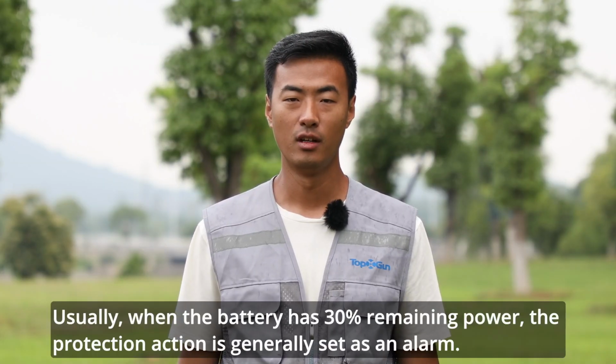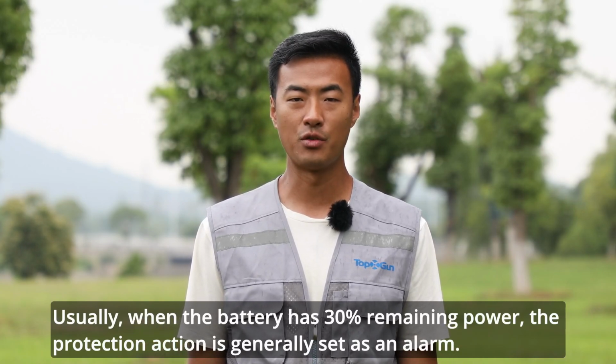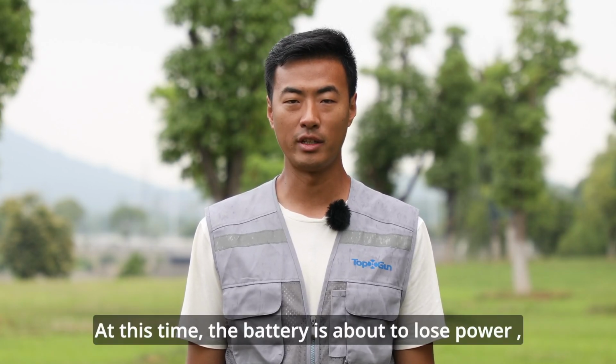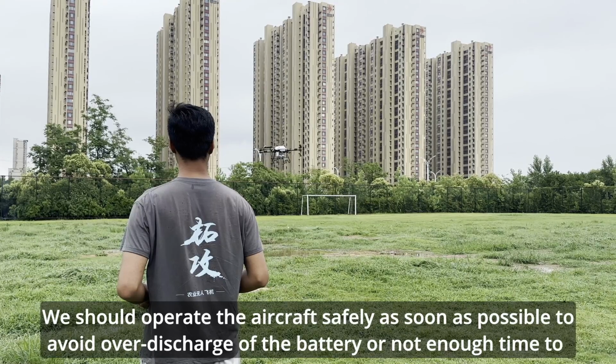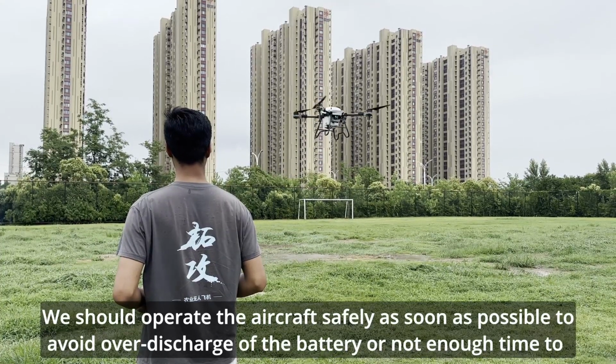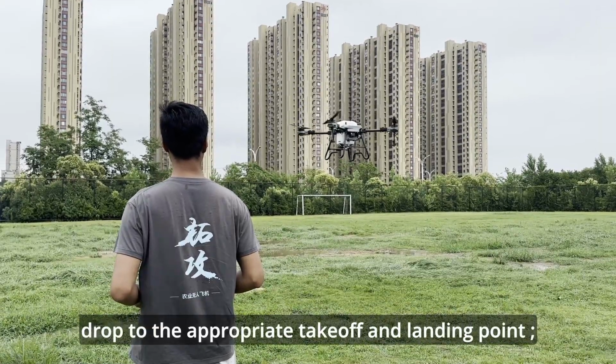Usually, when the battery has 30% remaining power, the protection action is generally set as an alarm. At this time, the battery is about to lose power. We should operate the aircraft safely as soon as possible to avoid over-discharge of the battery or not enough time to drop to the appropriate takeoff and landing point.